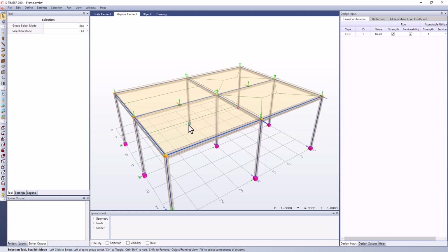What we've done is we specified a long one direction span that spans the long direction of the panel, and it's shedding those loads that are applied to this panel to each one of the members on each side. These are area load members. The direction is indicated by the edge of this tributary area, which shows that any loads that land in this area here are going to be shed to this beam, and any loads applied to this area here are also going to be shed to that beam, and the edge beams are going to have half of the tributary area.